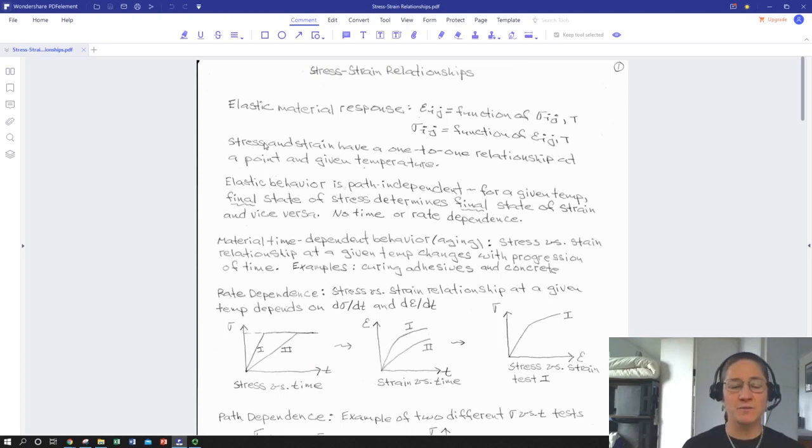Those of you who will use metals or specify different types of thermomechanical processing for metals will find that different types of heat treatment result in aging material behavior, which means time-dependent material behavior. Precipitation hardening of aluminum is a noteworthy one that you might encounter with aerospace materials.